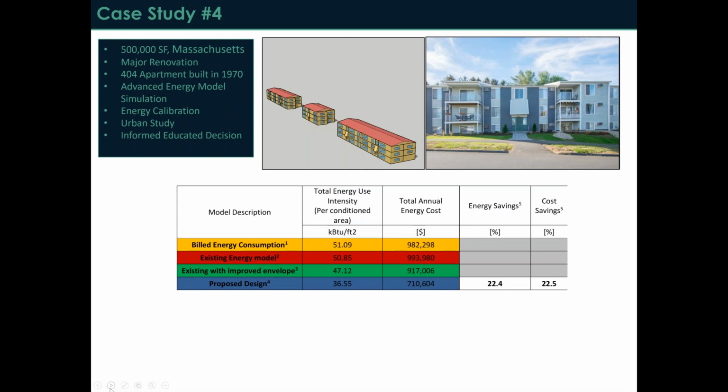So energy modeling shows that with only this table that we can see on the screen, with only one improvement in envelope, which was just patio door window replacement, which is the green line, with improvement envelope. And it was only patio door. That's the only change, I mean, all the glass type, all the glasses were improved, and then with the improvement in a mechanical system, using geothermal for that location.